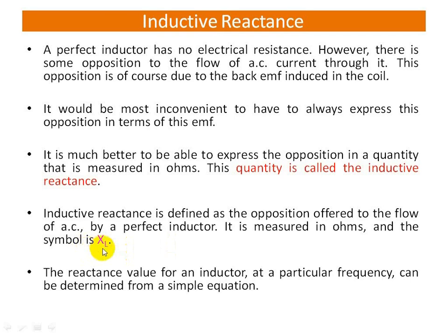I told you already that the induced EMF will be opposing current, but we are not going to express the opposing quantity in terms of EMF. It is inconvenient to express the opposition quantity in terms of voltage. That is why we use this quantity called inductive reactance as the quantity that opposes the flow of current. So this XL is directly proportional to the frequency.